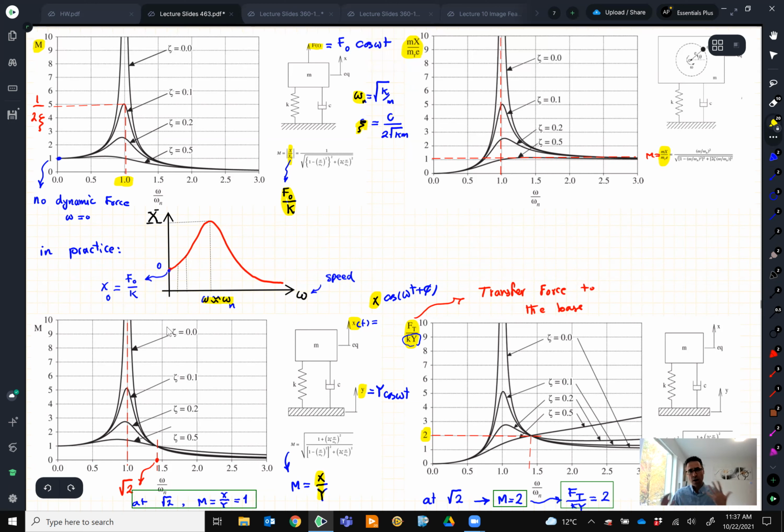Because remember, in a complex system, you don't actually have a nice K and nice M that you can divide and find the natural frequency, right? You have to do measurements, and you will see there is a peak. After that, the vibration becomes smaller and smaller, and eventually it goes very small, but you probably don't have the tool to go that fast, but you realize the trend.